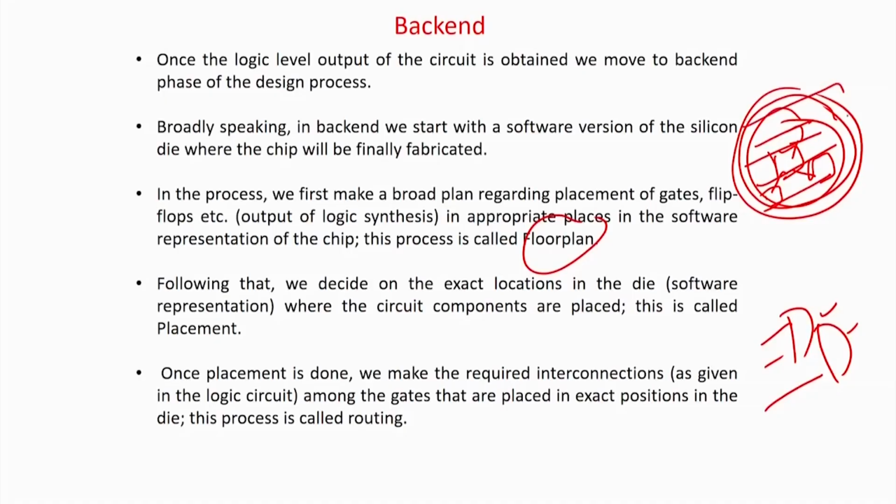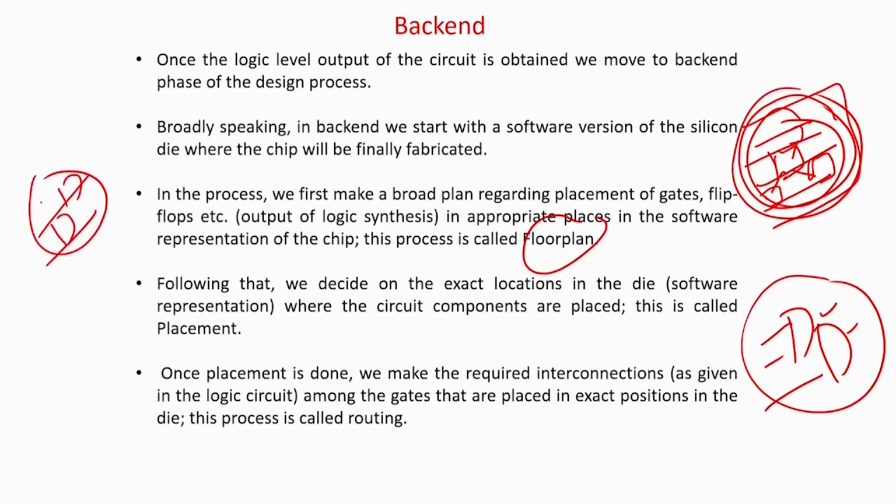Finally I should get this. It is not as nice as this, it's a die with some rows, and some gates are put here and there and some interconnections are done. That should also be in a reasonable space, all gates have to be put, placed and routed. And that has to be done in a reasonable amount of time, because the placement and routing should not take a huge amount of time, so that your design speed is higher.